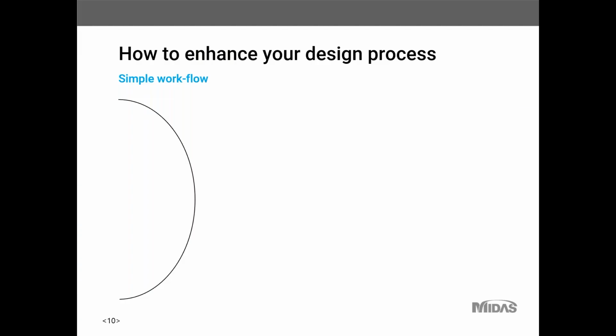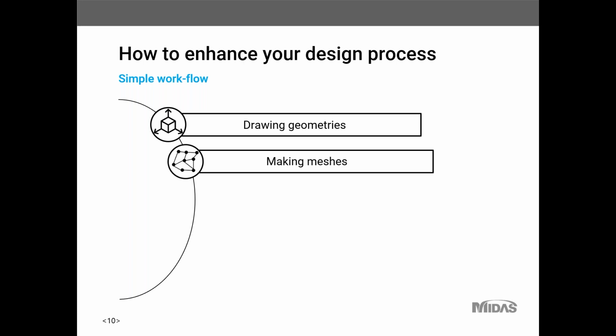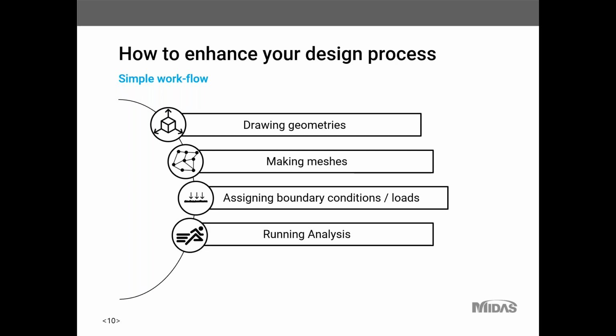Let's get to the point. If you have ever used FEM analysis, imagine the process in your head. First one is drawing geometries. Second is making meshes. Third one is assigning boundary conditions and load conditions. And finally, you will run the analysis and check the results. This is the regular work process for the FEM analysis.